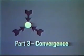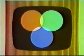Part 3 takes us through the 2 sequences of convergence adjustment, static and dynamic. The shadow mask color picture tube constructs the complete color picture out of 3 separate pictures, one in red, one in green and one in blue. It is essential that these three pictures register as accurately as possible. The registration can never be quite perfect, but it is possible to get results that do not show serious color fringing at normal viewing distances. This registration of the three color pictures is called convergence.